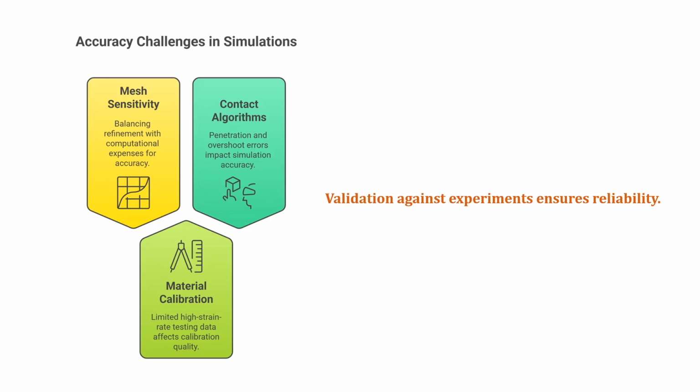But what will happen is that if we make our mesh very fine, then the total amount of time required to simulate the entire thing will go very high. So, there is always a balancing act between the mesh refinement and the computational expenses that we incur for the accuracy. To achieve a good mesh sensitivity is a key factor in any finite element simulation.